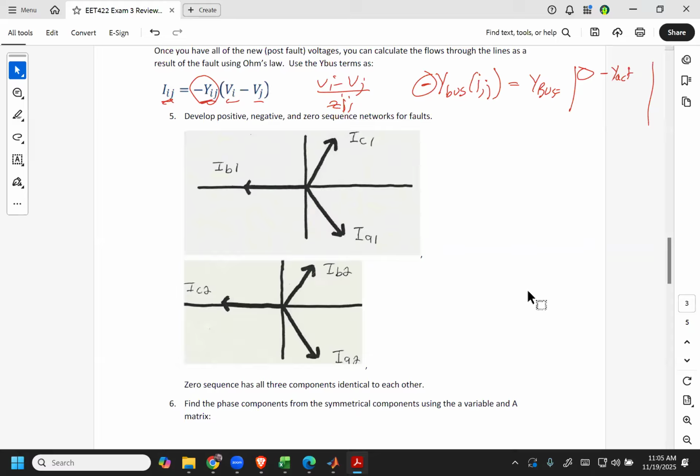One of the more difficult things moving forward is that now we have unbalanced analysis, particularly when we put in distribution systems, PV, or wind, and we distribute it. Now we have the possibility of a lot of unbalance in our system. As a result, we have to take a different approach to solve for fault currents. We can't just do symmetrical components.